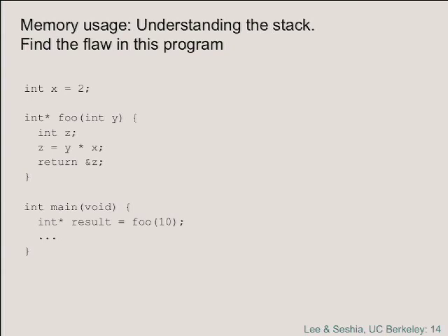So if you have any interrupts at all enabled in your program, then between this instruction and the next, you have no assurance that the stack was preserved. Okay? It's even worse in C because there's no notion of from one instruction to the next. You can't count on a single instruction in C executing atomically without being interrupted halfway through.